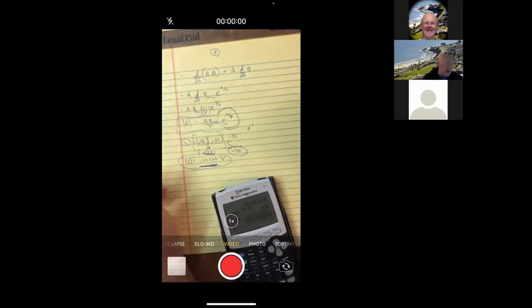And like I said, very common. So I guess I would describe this as when your field was first turned off, you had an EMF that's not real strong. It's only 28 thousandths of a volt, but it's measurable, noticeable. 2 seconds later, you're in the thousandths.